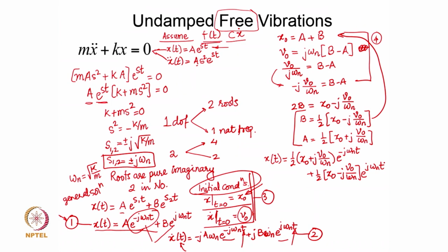It will be clear to you shortly what x naught and V naught actually mean physically. Obviously, these x naught and V naught are the initial conditions at t equal to 0, after which those displacements are withdrawn. That means they exist only at t equal to 0. Subsequent motion of the vibratory system happens on its own. That is what we call free vibration.